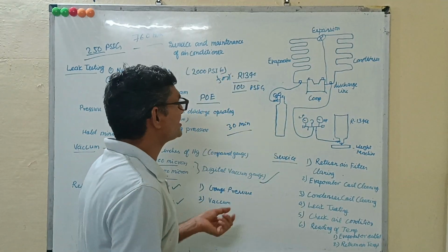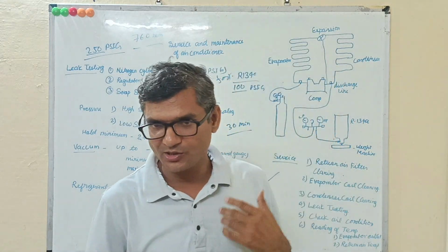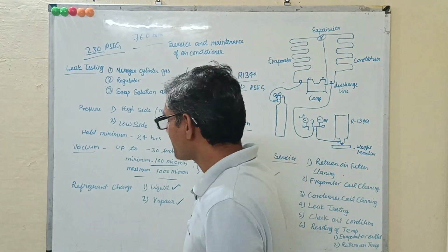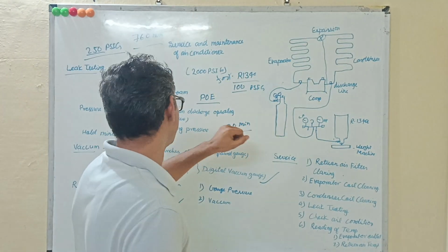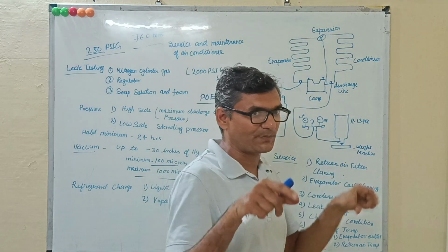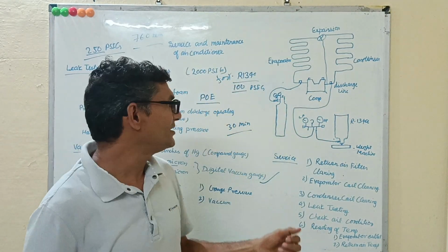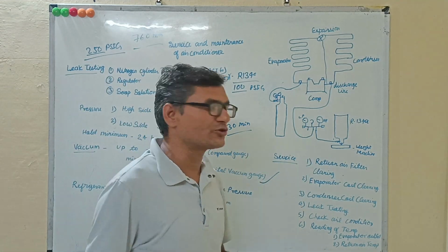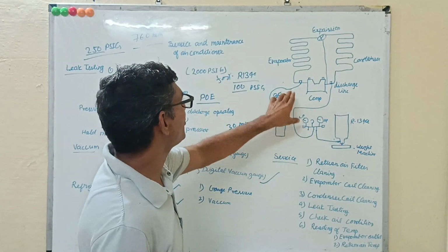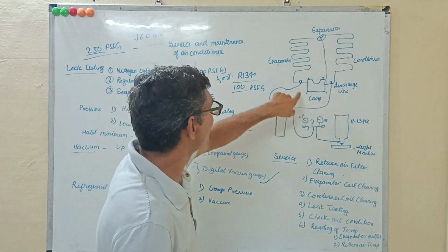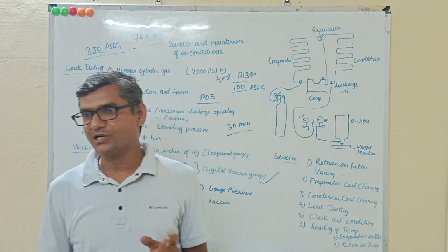Suppose we want to do vapor charge, meaning liquid charging is over and liquid is not going in any more, then we switch on the air conditioner. Once switched on, we have to check the proper pressure corresponding to temperature. Suppose all are equal, okay, no problem. Suppose less pressure is there, then we again have to top up the vapor. For vapor, we connect here, disconnect this one and connect here. But weight is also required, because we are charging accurately.